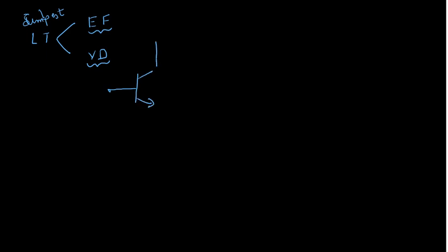So this is an emitter follower circuit. Why do we need an emitter follower? Because we don't want the AC component of your input signal to be amplified. Whatever input we provide, we get the same output in AC, but we just want to shift the DC component, right? That is why we are using an emitter follower along with the voltage divider.